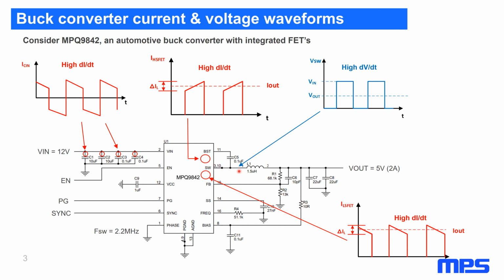Most of us who've been working with power electronics and DC to DC converters have probably measured a switch node once or more. This is the very common waveform we see. It looks like a square wave or a rectangular wave where the buck converter is switching off of the 12-volt supply, and it transitions between close to 0 volts up to VIN. And the duty cycle of this waveform, how long it turns on and how long it turns off, will ultimately determine what our VOUT is that we're trying to regulate here.